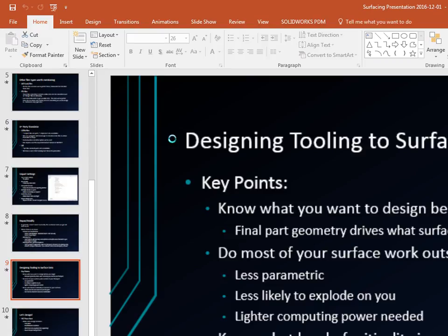Hey Dale, have you ever done a lofted surface where you just pick the edge of each of the short sides of the rectangles as you're creating your loft, and just create one loft? Yep. Go into your loft, create a loft, now start on the short side, but on the other end of it. Like this? Yeah, go from here. Then just keep selecting them and it'll build one. Oh, yeah, you could do that. Okay, so do this sort of action and make it one loft. I don't know if it's better.